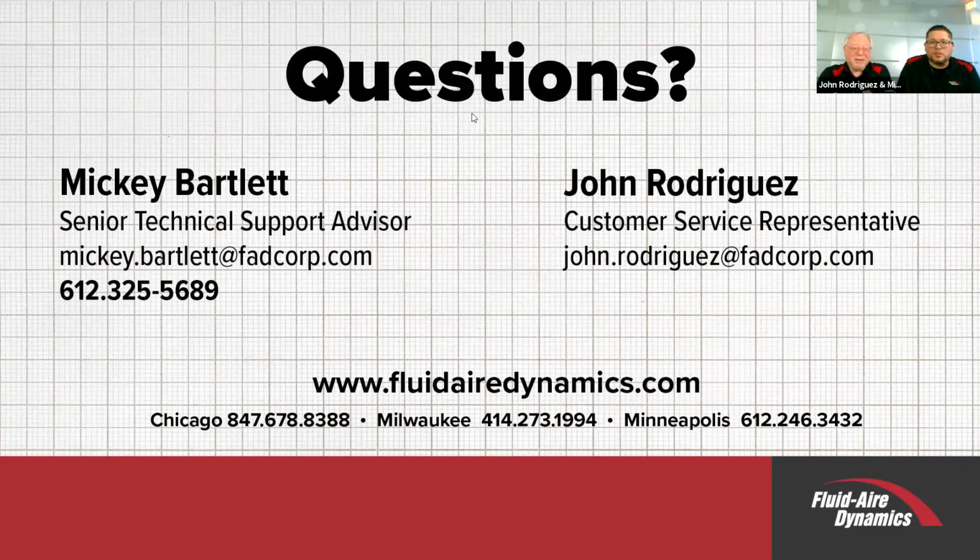Another question here: when to use master controls? I am assuming you're talking about a controller that's going to control all your air compressors. Having multiple compressors, even of different sizes, how do you choose which machine should be on at any given time? You may have the wrong combination on, and these controllers allow you to fix that. If you think you have air compressors running that don't need to be running, or you can't set the pressures on your compressors to allow that to happen, then a master controller is probably something you should be looking at, especially when you have three or more air compressors. That becomes a little bit easier to manage with a master controller.